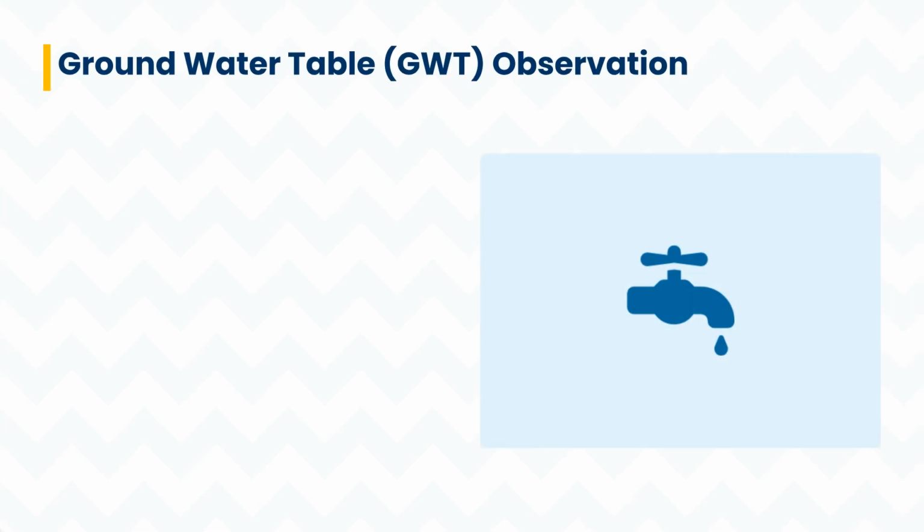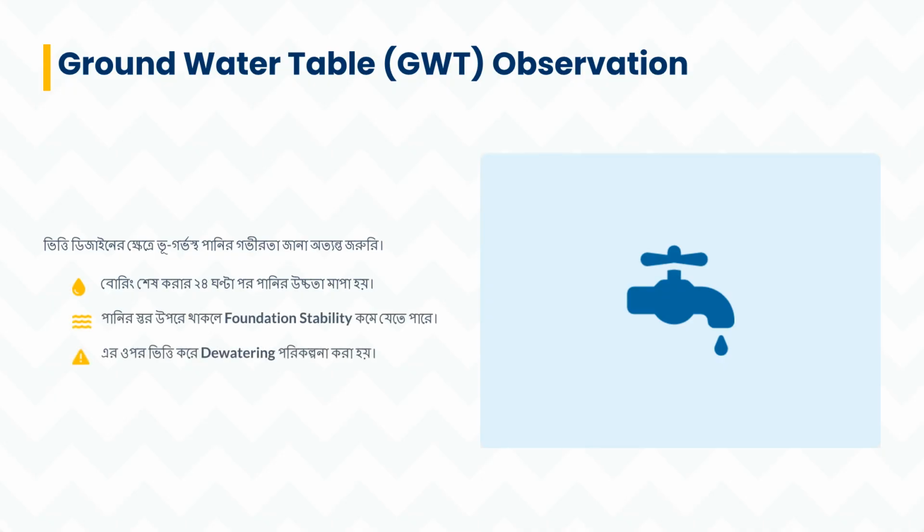Groundwater table observation is crucial for foundation design. The water level is measured 24 hours after boring is complete. If the water table is high, foundation stability may decrease, requiring dewatering planning.